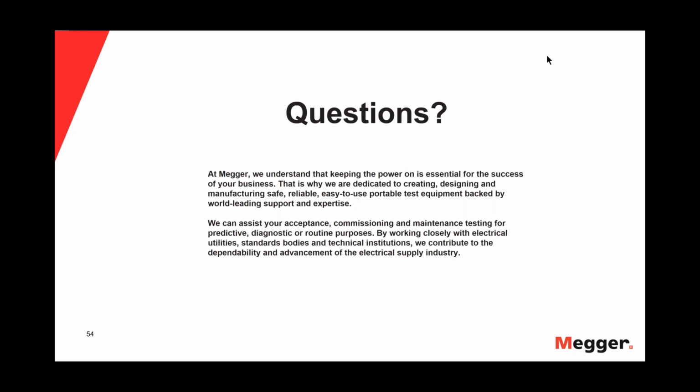All right. Well, Henning, while I have you here, if I have one phase of 3 with higher leakage current than others, but not breakdown during high voltage tests, what's the proper action? Well, so you don't really have a fault on the cable yet, right? It's just you have one phase that has a higher leakage current. So the question is, it will have a potential to fail in the future.